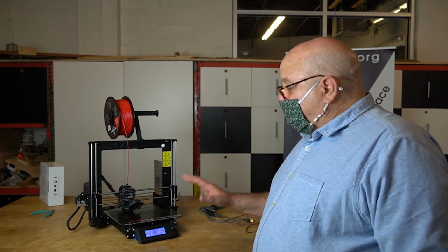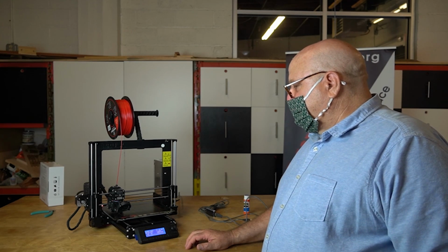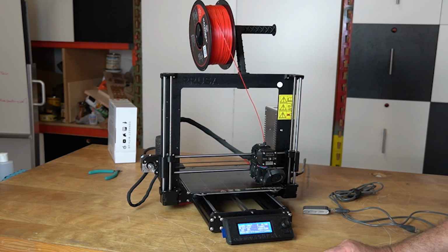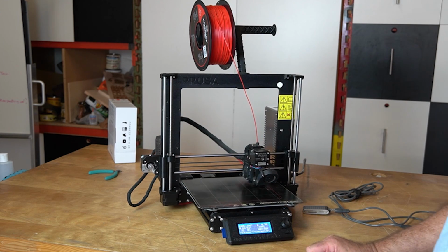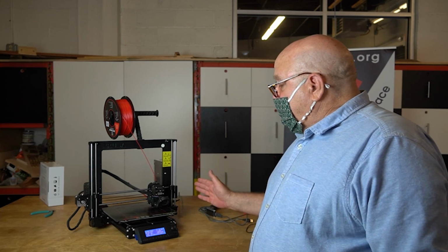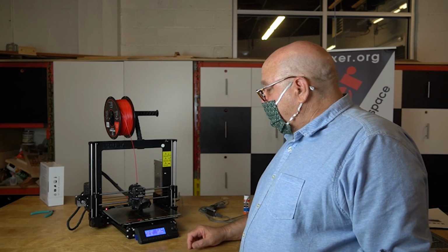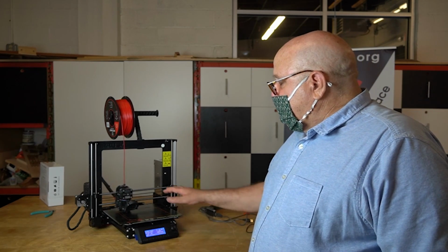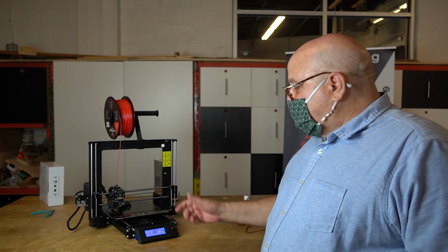Now, it's important to make sure you do watch the first 5 or 10 minutes of the first layer, because if the first layer does not come down properly, then you may have problems with your print job. Things that could happen: maybe the PLA is not sticking to the bed, which would imply you need some more glue, or the heads are having some issues and the PLA is chipping or pulling or stretching improperly. But the key is just to watch it. You'll know if it's not in there properly or not. And again, that's going to take 5 or 10 minutes. I'm not going to show the whole thing. But if it does have a problem, you have to stop it.